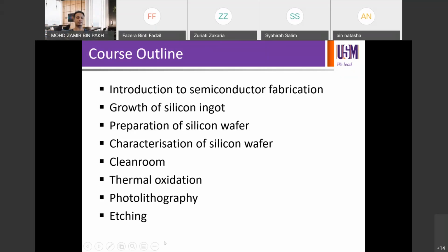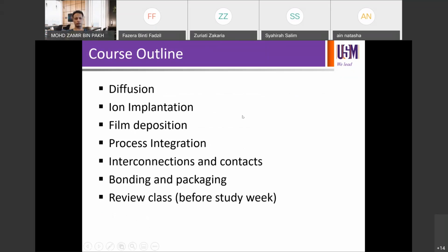Yeah, wet etching, right? In order to produce silicon nanowires. So you've gone through diffusion in order to learn how you actually dope your sample, how you form a junction, how you get P plus, P minus, or intrinsic. We learned about intrinsic as well if you don't dope your wafer at all. And how do you end up characterizing the junction that you have formed in the diffusion process?